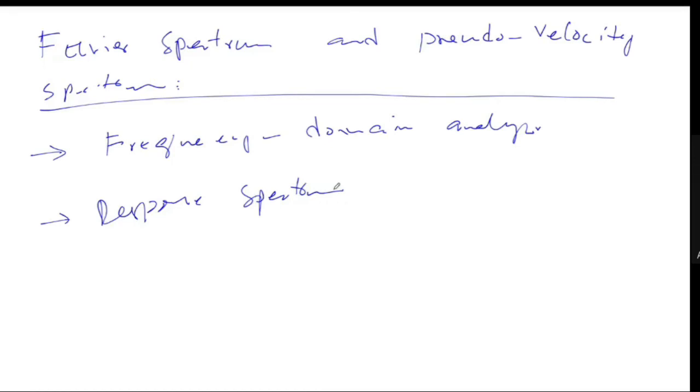So the frequency domain, the Fourier amplitude, is just giving you the idea of the frequency content of the input. But the response spectrum is giving you information both on the vibration period or the frequency of the input and also the response of the system.